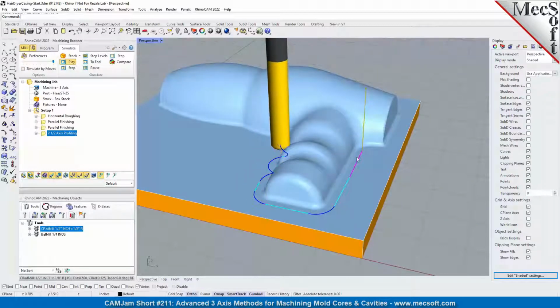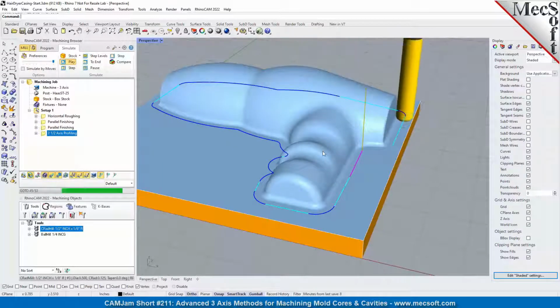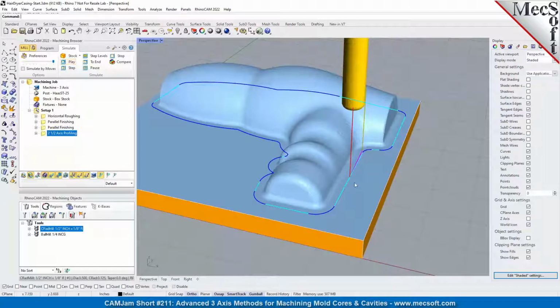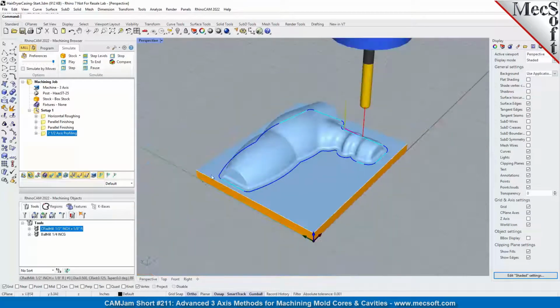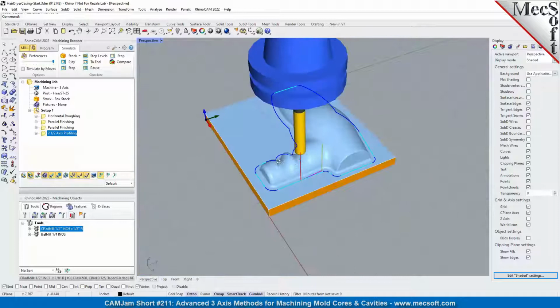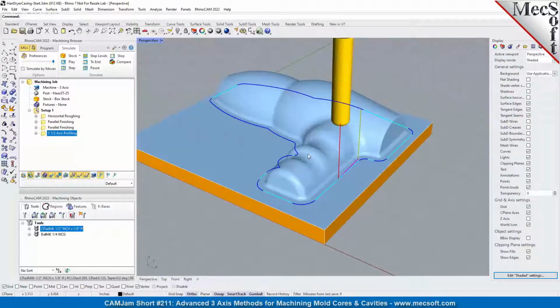So you see that it didn't really cut anything on the contoured areas because it's not all the way over and touching the part. So it didn't cut anything here, but it cleaned up the areas that have the vertical walls. So we have 1/8 inch radius here already, 1/8 inch radius there. So how are we going to get this fillet radius in there?